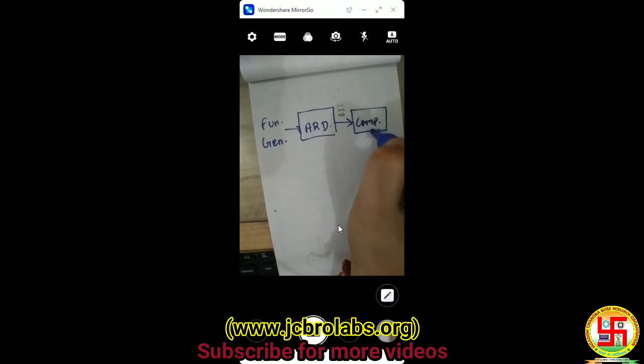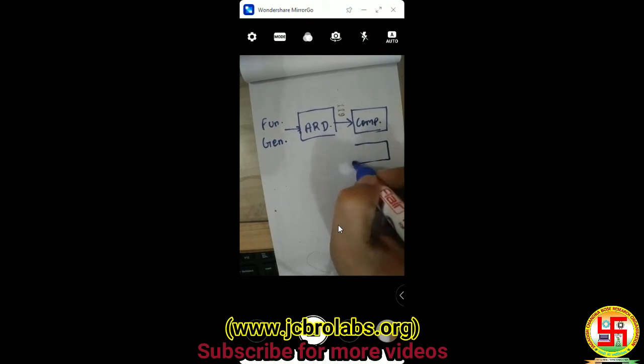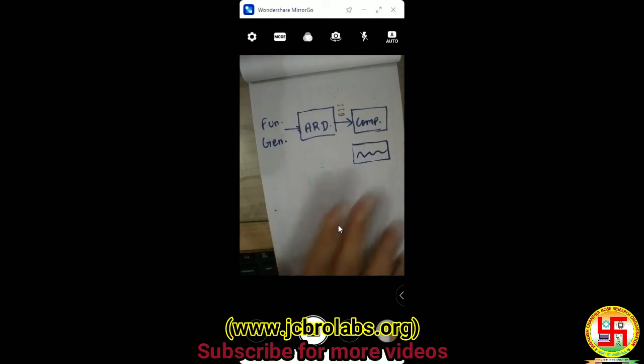And on this computer, we will show the waveform in Arduino serial plotter. So in Arduino serial plotter, we will be showing the filtered waveform. Now when we are going to sample the data with this Arduino, we have to know what sampling frequency can be achieved from this Arduino in real time, so that we can use that particular sampling frequency in our Matlab code in order to generate the filter coefficients. Okay, so yeah, that's cool.